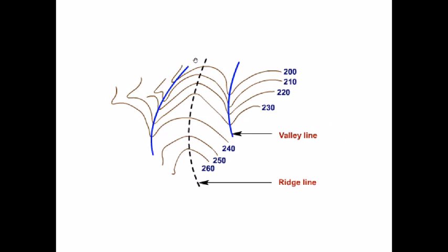So like this over here, two V shapes. That means we have two valley lines, and in the center we have the other shapes, which are not as steep as we have in a valley line. So milder shapes and successive ones, they represent a ridge line, which is a mountain top, and over here you have a depression, which is a valley.